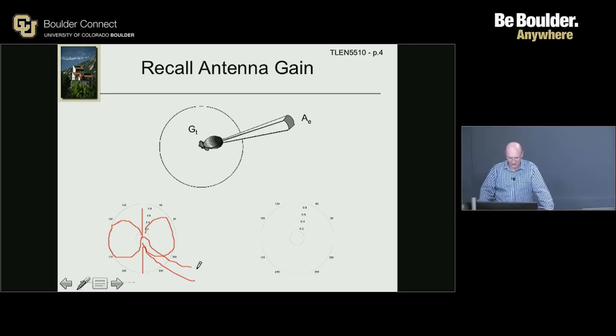No, the antenna gain is a gain in a certain direction with respect to an ideally isotropic antenna. So for instance, if you had an antenna, and such an antenna doesn't exist, we can't make one that transmits ideally isotropically, and then you make another antenna, well, it has a certain gain in a different direction. In the boresight, usually the gain is greater than 0 dB, because you want it, or dBi for isotropic.